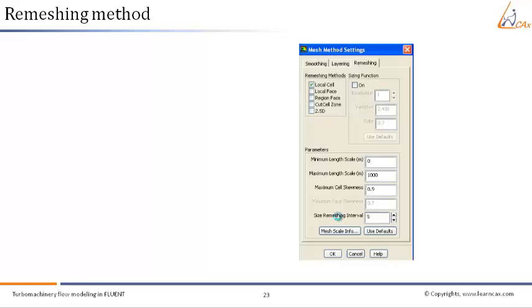On zones with triangular or tetrahedral mesh, the spring based smoothing method is normally used. When the boundary displacement is large compared to the local cell sizes, the cell quality can deteriorate or the cells can become degenerate. This will invalidate the mesh, which will lead to convergence problems due to negative cell volumes. To resolve this, Fluent collects cells that violate the skewness or size criteria and locally remeshes the collected cells or faces. If the new cells or faces satisfy the skewness criteria, the mesh is locally updated with the new mesh cells, otherwise the new cells are discarded. This is known as remeshing.